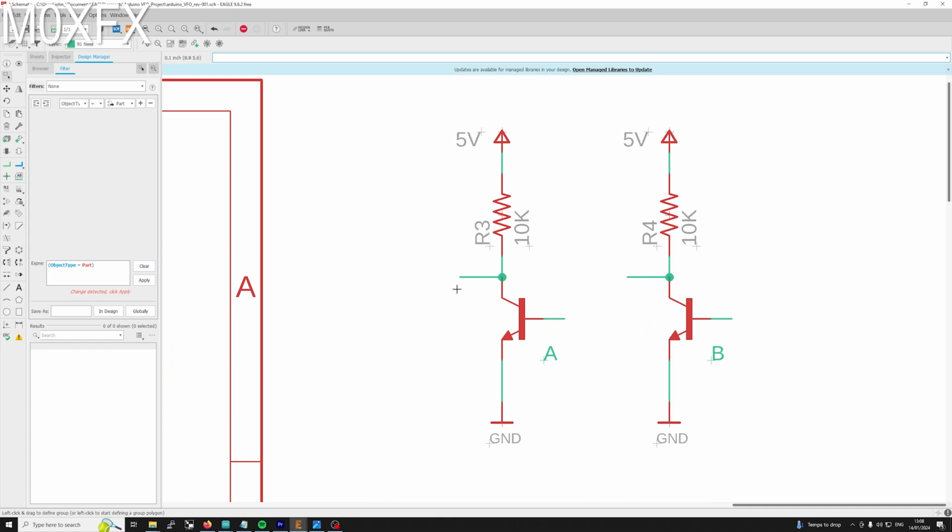Now this is obviously what's inside. At the top here, these two 10k resistors are our external pull-up resistors. So on the base of this transistor, if that goes high and switches the transistor on, at this point it will pull the voltage low. If we're sending a square wave here, we'll get a square wave out here. The output will be inverse to what's coming in on the base.